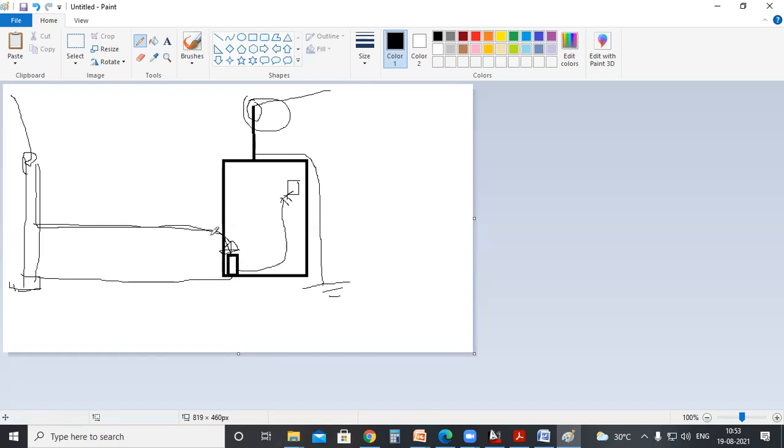Okay, is that clear? For a transformer located outside in the outdoor area, we'll have another surge protective device connected in parallel. This will earth the lightning current. Okay, so this one was for the building. Here this application is different. The surge protective device's physical appearance would be different. This one will be a compact one.